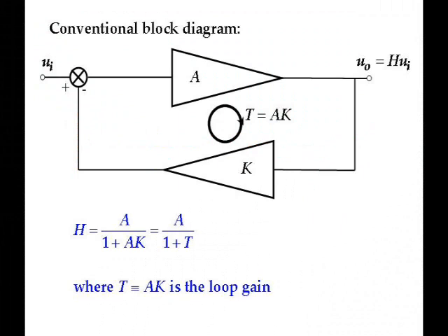Feedback systems are usually designed with the familiar single-loop block diagram in mind. That is, the major loop feedback path is designed to have a transmission function such that the specified gain is achieved in the presence of non-infinite major loop gain. Various non-idealities, such as unavoidable minor loops and direct forward transmission, make the single-loop block diagram progressively less useful, especially